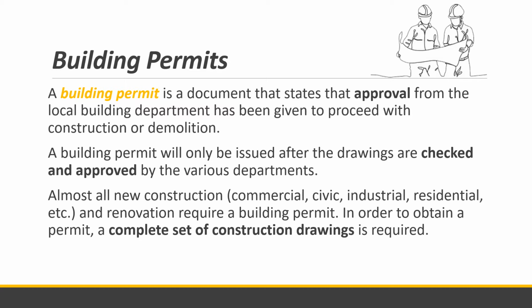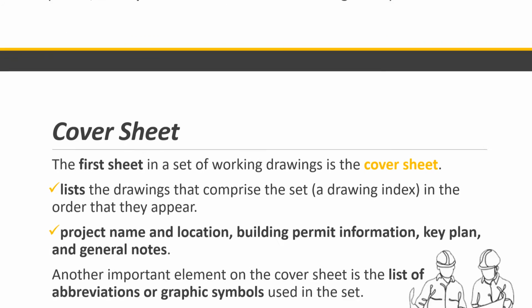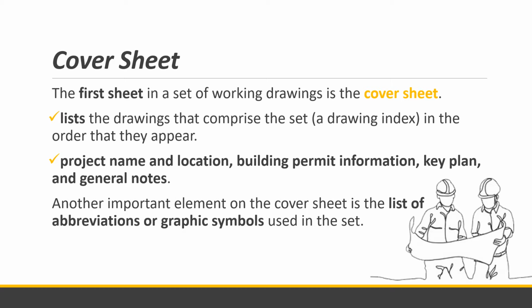Okay? So next is the construction drawing set. First is the cover sheet. The cover sheet is the first sheet in a set of working drawings. It shows a list of drawings that comprises the drawing set, or a drawing index, in the order that they appear.